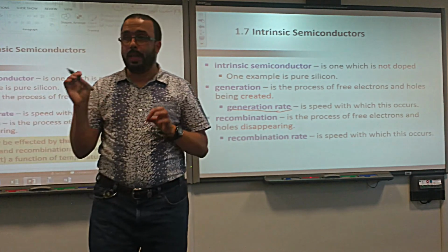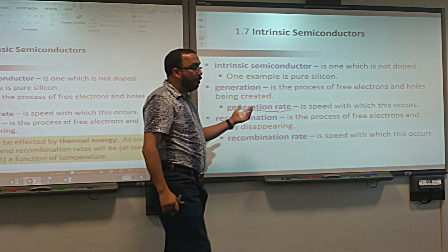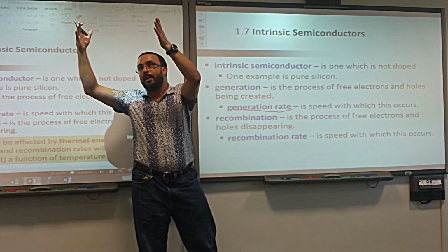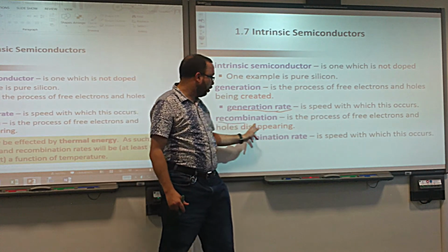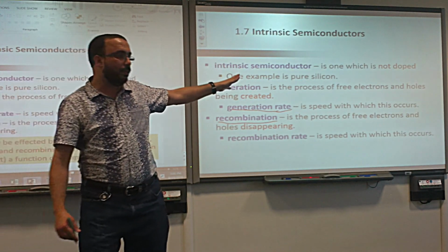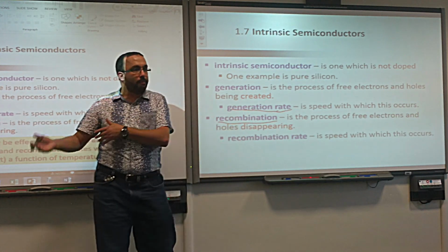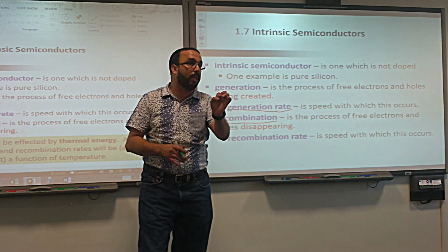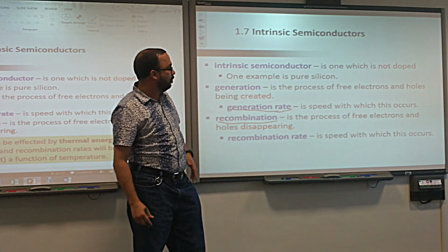And something more happens. If an electron finds its position, meaning a hole, they do what we call a recombination. Now, that electron will not be freely available anymore, and it will be in a bond, for example, or something like that. So it will disappear from the table of free electrons. It will not be a free electron anymore. That's it. It's gone. So we call that process a recombination. It now becomes like any electron that is responsible for any bond. Okay? It will be attached to an atom. So the generation has a rate. The recombination also has a rate. It means how many free electrons and holes die per unit volume, per unit time. Let's say 1 million electrons get generated in 1 cubic centimeter per second. That's the rate. Okay? We create them over a certain period of time, over a certain volume. Bingo.